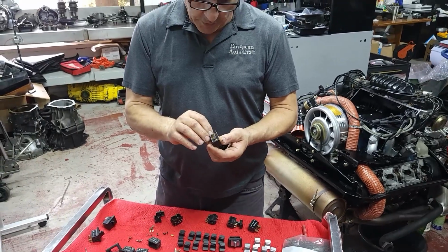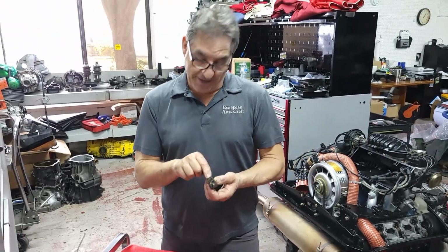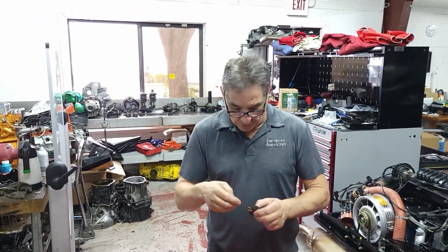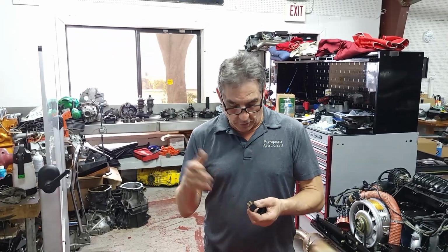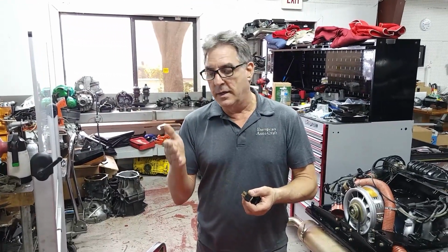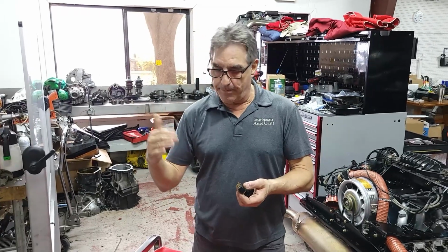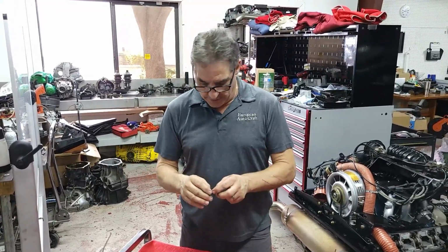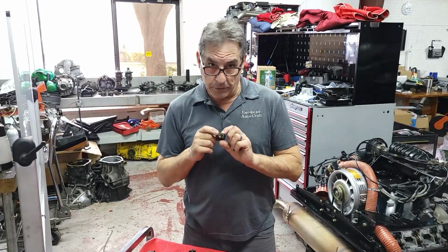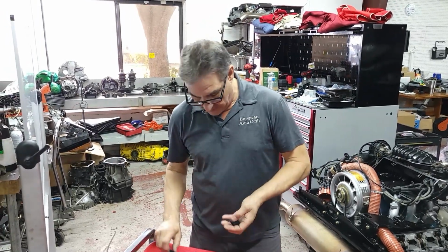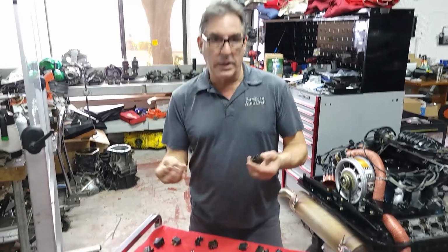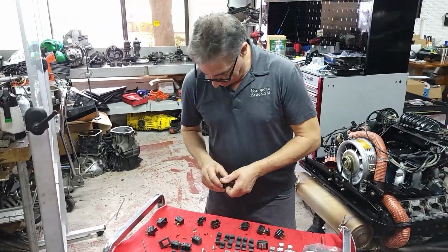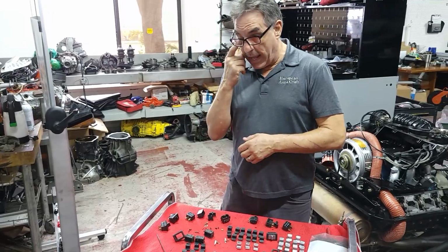If you're going to replace your window switch, you better get these right, because all kinds of things can happen if you put the wires on wrong. The window will just go down on its own and stay on, causing the circuit breaker to trip and make the window energize and then de-energize. So you got to be very careful with these wires in the color code when you take them off. The later ones are simple. One connector, it only goes on one way. So let's get down to what happens here.